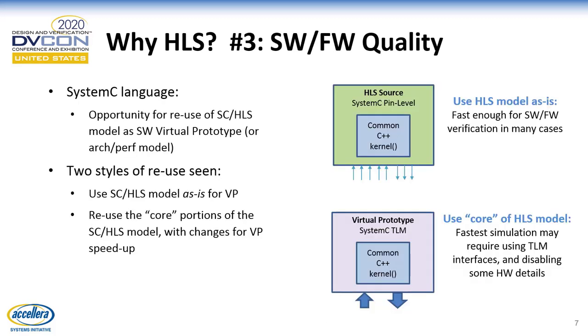The third reason that I don't always see with design teams, but it's becoming a bit more popular, is to reuse a lot of this code in other contexts. So you'll see many virtual prototypes out there are done using SystemC. Getting a common language here for your design source as well can give you opportunities to reuse that in the VP space. So you can test your firmware because this runs much faster than RTL. It varies a lot on your design, what type it is, but in general, you're about 100 times faster than RTL.